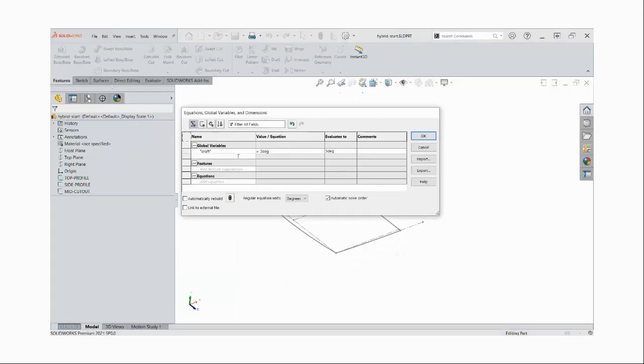Also, the wall thickness is another parameter that I'm going to be reusing frequently. So I'm going to call this just wall, tab, and this is going to be taboo for some people, but just from my experience, because the vendors I worked with are overseas, I always think of the wall thickness in millimeters, even though I'm modeling in inches.